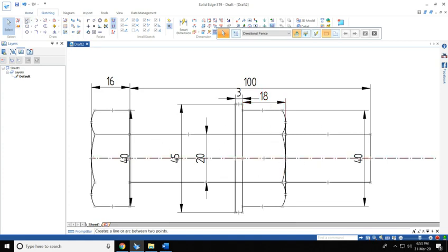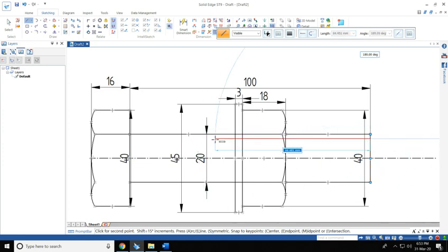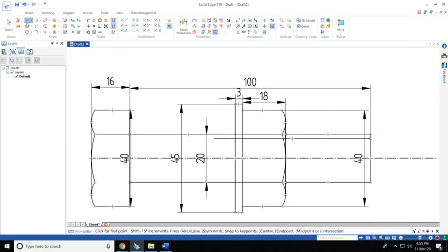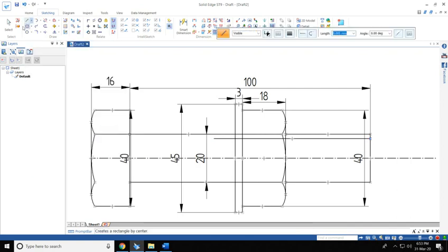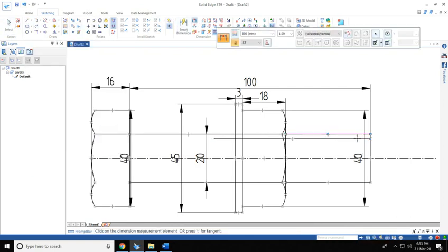Okay, now we need to draw the thread. So thread, let us take it as about 65 length thread. Okay, and then you can't really draw thread here, like how you draw in your thread forms, because this is very small dimension, it is very hard to draw, so you just represent it as one small line. Okay, so we'll take the thickness of thread to be about 2.